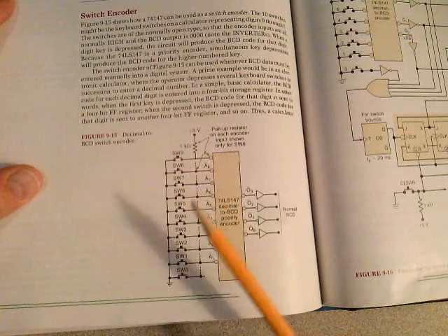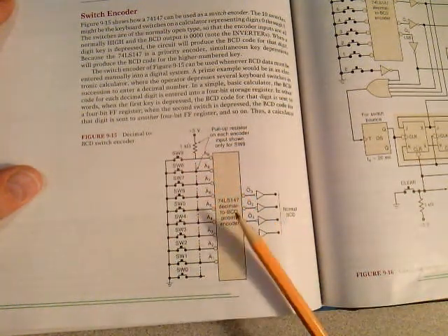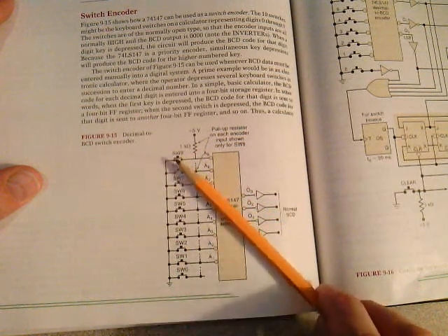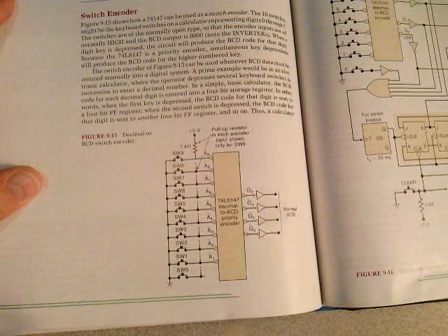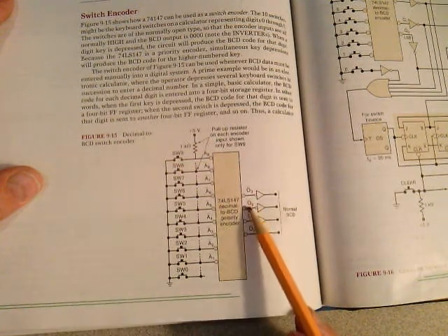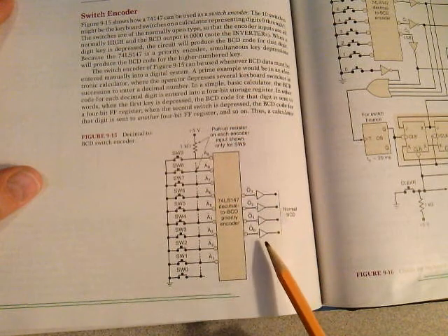So basically here's your 0 through 9. This is an encoder, so only one of these is going to go active. It's a priority encoder, so only one of these buttons you push, and based on whatever button you push, you get a low active output. Notice it gives you the low state here. But I'm just using these inverters here.